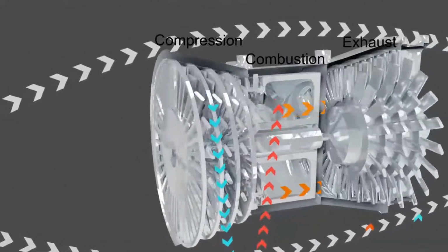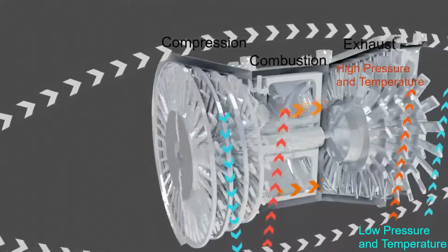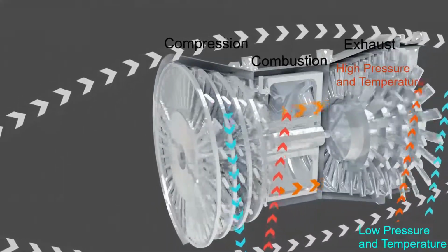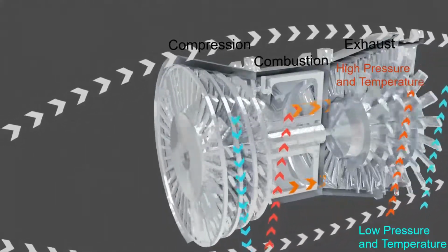The energy released from ignition is absorbed by a series of turbines. These turbines quickly increase in diameter as stress and temperature variations are high here. Channels through the blades provide a thin layer of air for cooling.